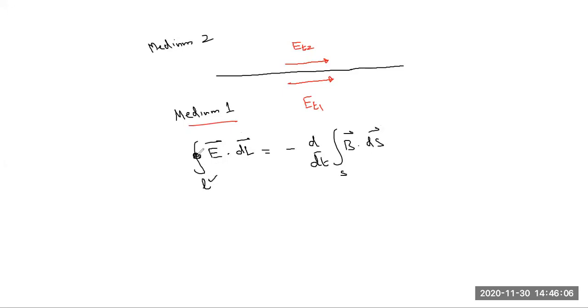Whenever you have a closed path, a closed path can always make some kind of a surface. So that is the surface. And we also included the hypothetical magnetic current density. So if there is a magnetic current density passing through the surface, it can also produce this closed line integral. And you all know that the left-hand side is basically EMF, EMF induced because of either changing magnetic flux or because of the magnetic current that is passing through the surface.